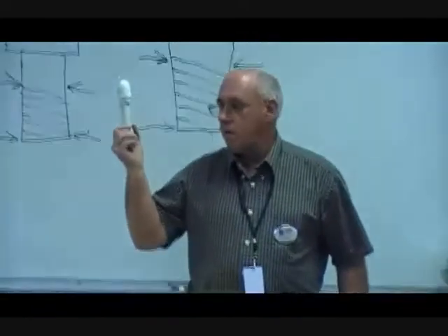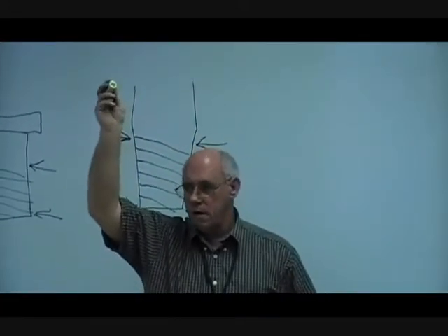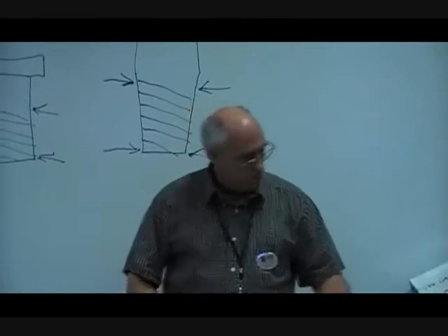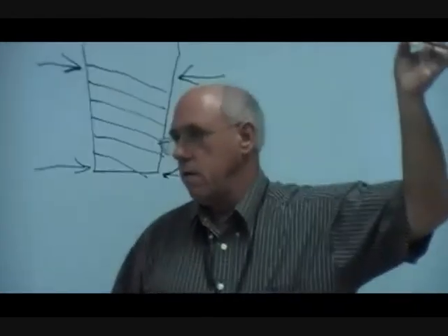Now, PVC is very good for cold water. You don't want to use it for hot water. CPVC, a little different in the color, different in the size. That should be used for hot water. You can use the PVC for hot or cold. A lot of people do.